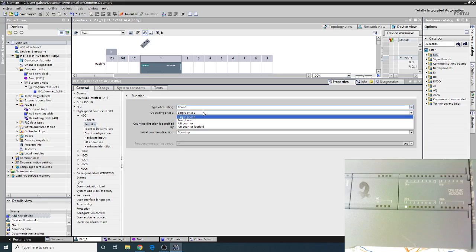And by doing an A/B encoder, it can actually determine which direction it's going by the pattern of A/B bits. There's actually a specific pattern to it. I think it's no signal, A signal on, B signal on, A signal off, B signal off. So there are 4 distinct stages: no signal, just A, A and B, just B, no signal. So there are 4 distinct phases.